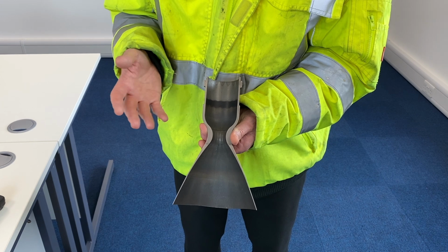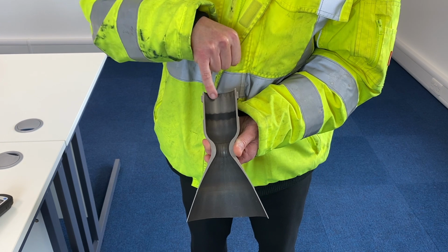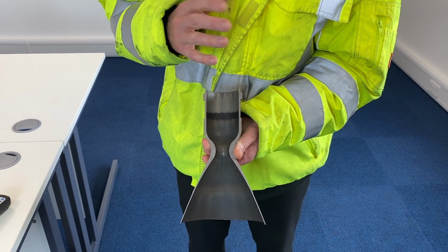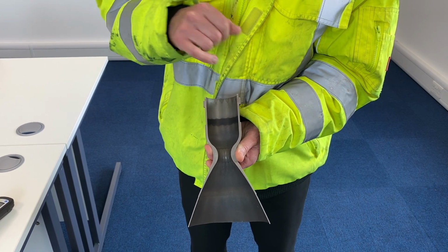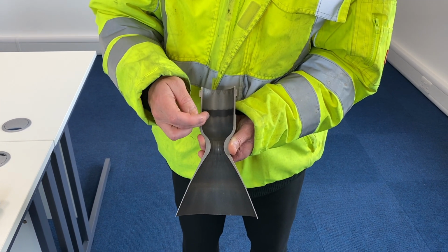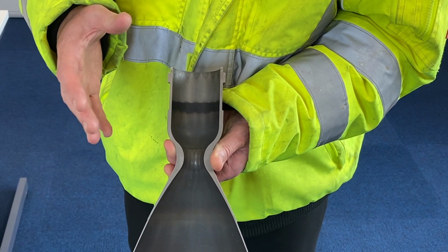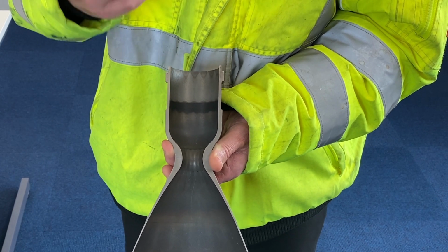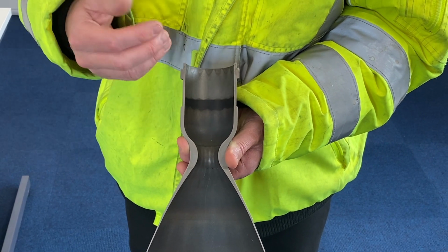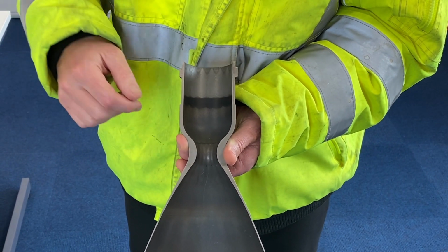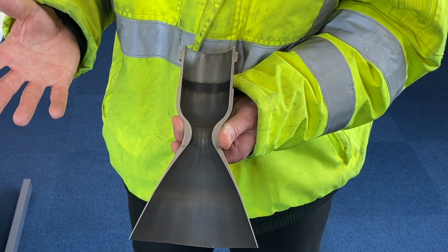So we need to do some kind of cooling to ensure that the metal doesn't melt, and we do that by spraying fuel onto the inside of the combustion chamber. That does two things. One, it forms a film, which you can see by these petal patterns, but once it's boiled, it also forms a gas layer, which is downstream of the liquid layer. Both the action of the liquid flowing over the surface and also the gas which is formed, insulate the surface from the main combustion flow and keep it to a peak temperature of about 1350 degrees C.